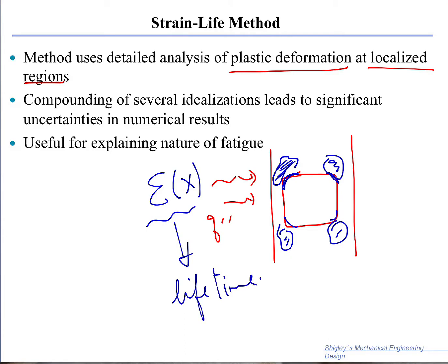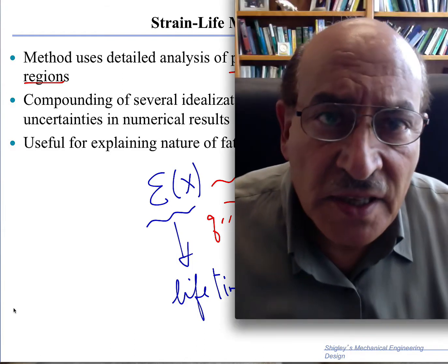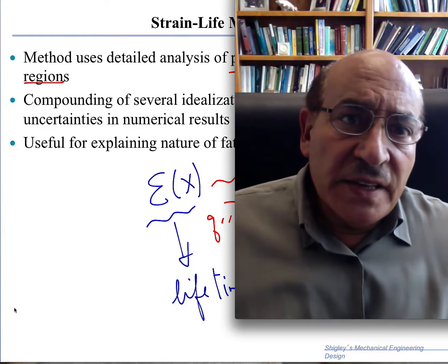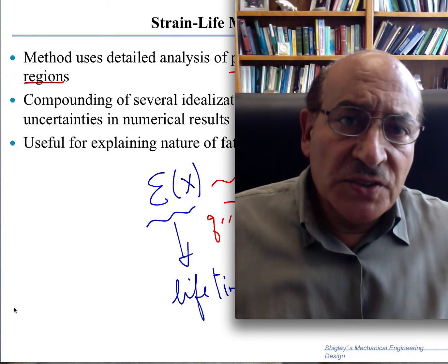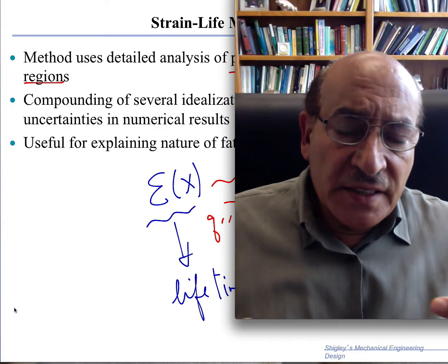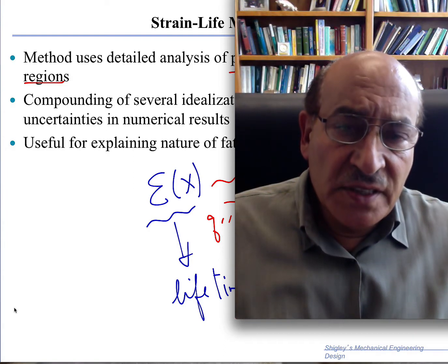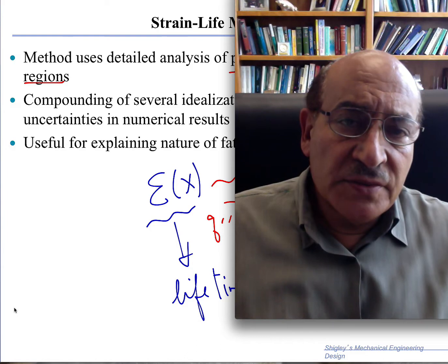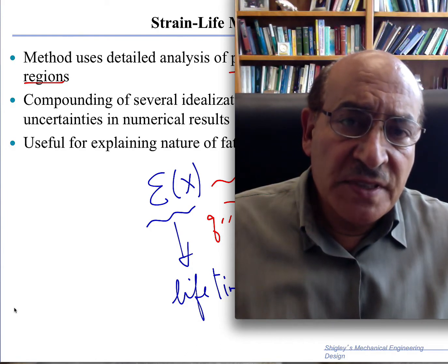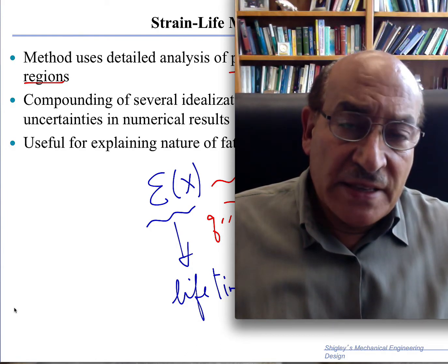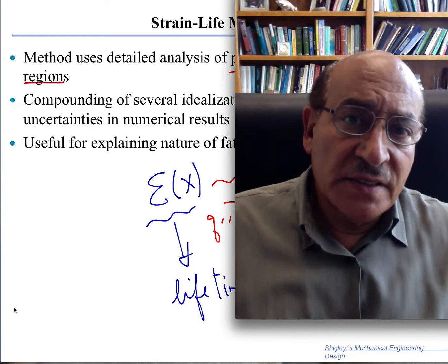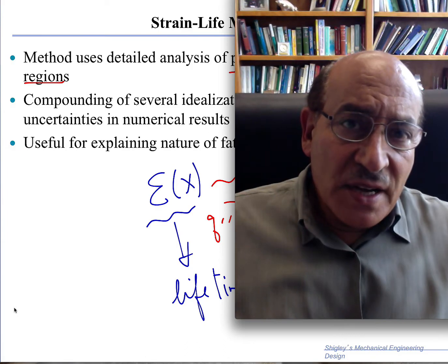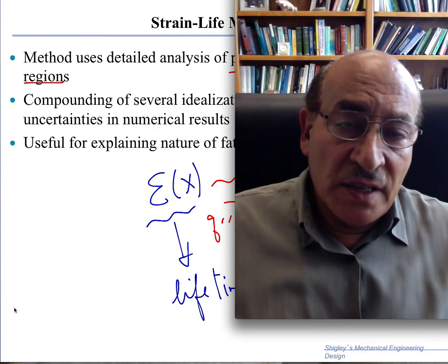So the idea here is that this type of approach is very detailed and takes into account the cyclic nature of plastic deformation, and it takes knowledge of running computer programs using elastoplasticity and accumulation of the strain from cycle to cycle.